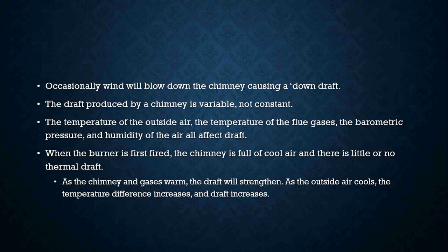Which kind of makes it very interesting when it comes to setting up an oil-fired piece of equipment, is that one day you can get it set up to maybe operate at 86% efficient, but in reality, maybe the next day or a day or two down the road, because the flue gas temperature has changed, the barometric pressure has changed, the humidity in the air has changed, the operation of that furnace now changes.